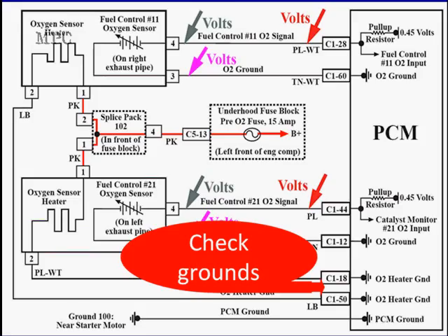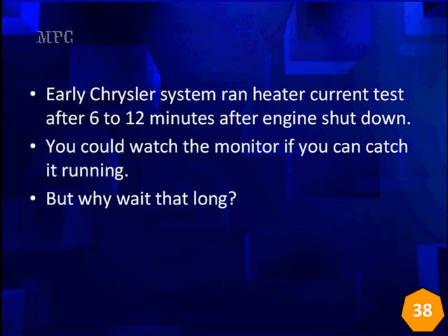Not all vehicles have that. If you have a problem where you can't get a good current flow, check for normal grounds. You have to have good grounds in order for them to draw full current flow.